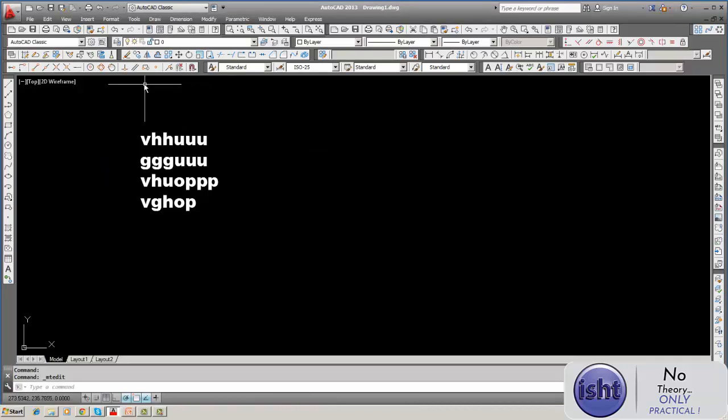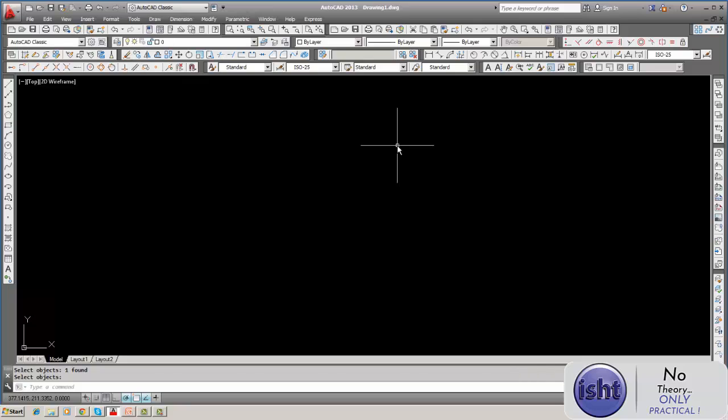Okay, this is how text edition, mtext works. There are basically only 2 commands in there, text and mtext. Text is also very rarely used. Mtext, if you are familiar, and Word document editing you are familiar, that's more than enough. So we'll be able to do text edition.